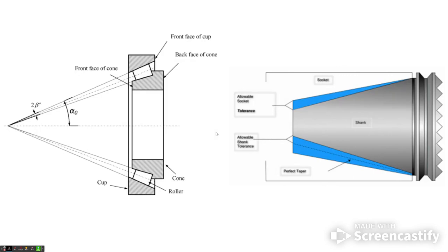Another part here, when we're talking about cones or angularity, is the same type of thing, especially with our roller bearings or ball bearings. You can see some tolerance zones there. So this was a good one to show you how this might be applied, and how we might get some different radial movement in ball bearings. Of course, the looser that ball bearing is, the more chance that it's probably going to prematurely wear out, and we're going to have to replace it more often.